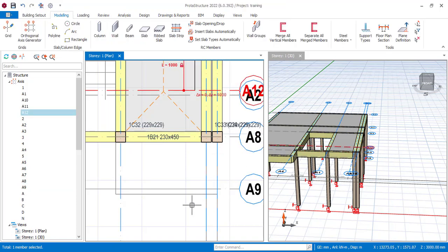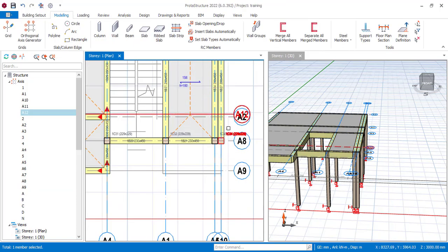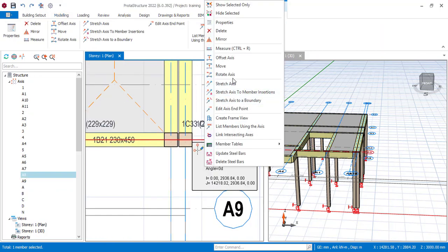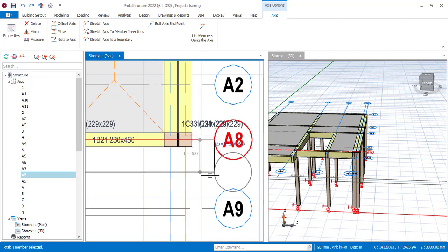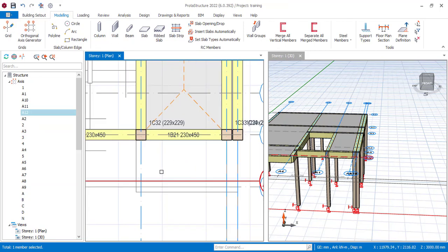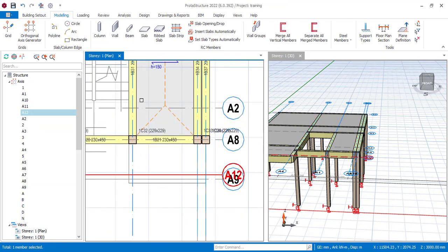In that case, mind you, whenever you want to offset, make sure you take note. If you are going down, it's always negative, so it's going to be minus 1000, and then I will type it in and click enter. Now you can see minus 1000 is what I have here, so I can simply insert.